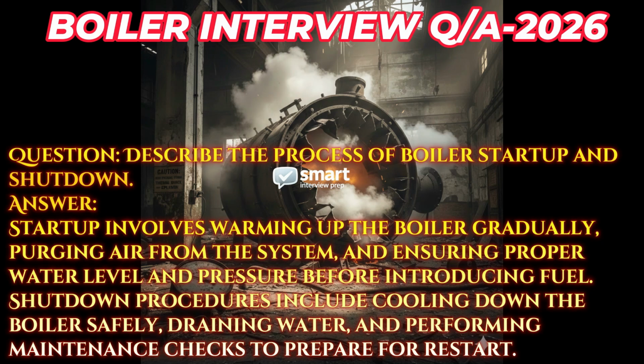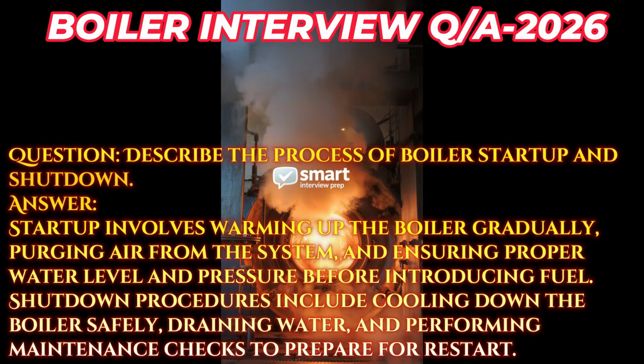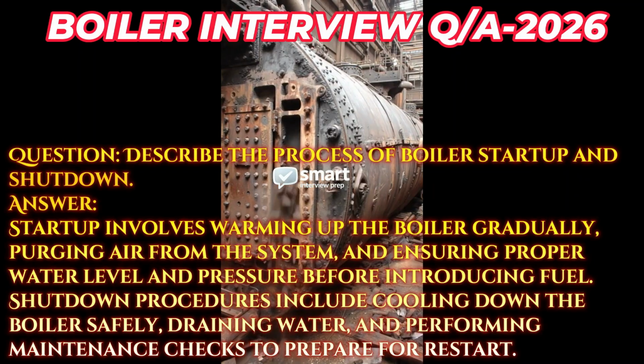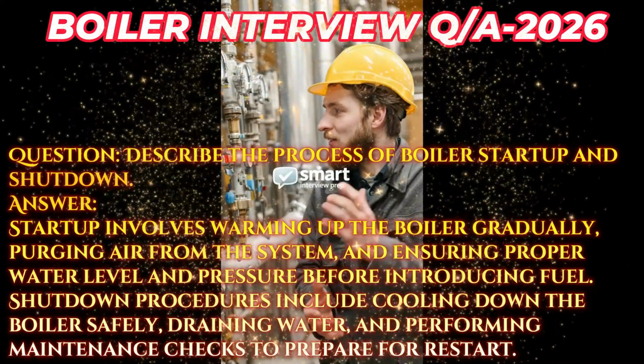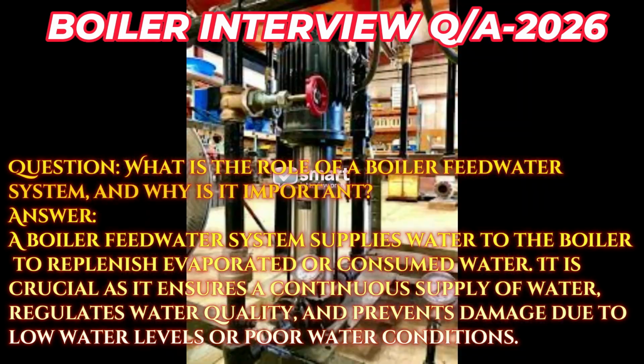Answer. Startup involves warming up the boiler gradually, purging air from the system, and ensuring proper water level and pressure before introducing fuel. Shutdown procedures include cooling down the boiler safely, draining water, and performing maintenance checks to prepare for restart. Question. What is the role of a boiler feedwater system, and why is it important?